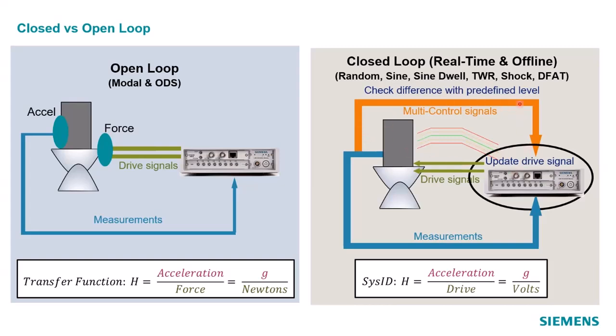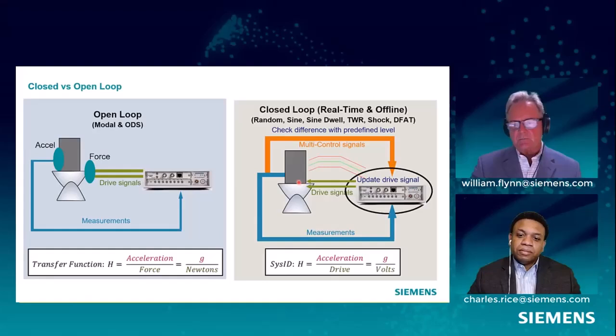So that's in a closed loop fashion, but we can also do some measurements over here, maybe some monitoring channels or some other channels like strain gauges or temperatures or things like that, that also we might want to measure as we're controlling this to, again, expose our structure to those kind of environmental conditions and measure responses around the structure.